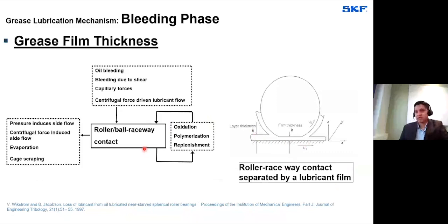As I said in the beginning, if you have a good film thickness for a long period of time, then you will have good grease performance, and that means good bearing performance. To maintain a healthy film thickness, there are different aspects at play here. A few aspects contribute to the formation of the film thickness, and a few result in the depletion of the film thickness.